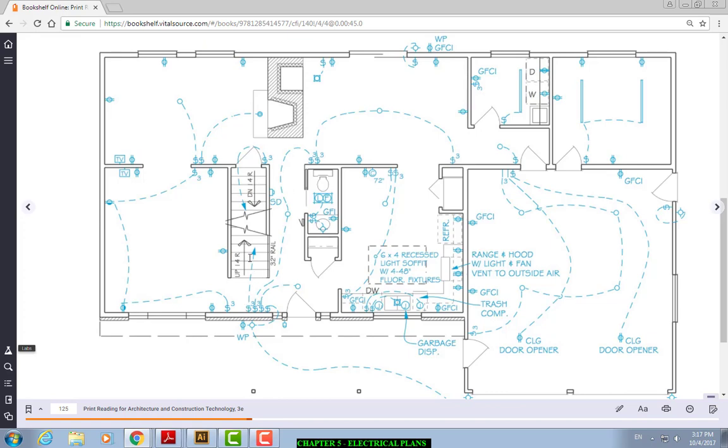This right here turns on the light for the stairs, and also on top you have another one. Or is it? It's up. Yeah, I think you have two though. I think this probably has a basement and a second floor. So from here you go up to the second floor. From the back you go down to the basement. So here you have a three-way switch. More than likely there's another one at the bottom.